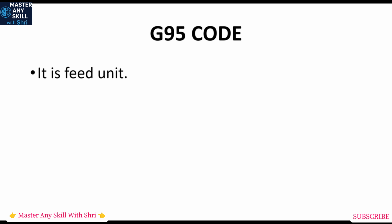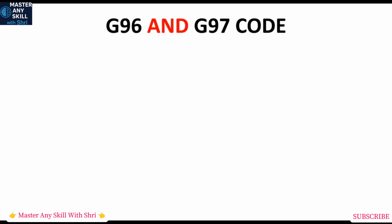So our next code is G95. It is the feed unit. With the help of G95, we tell the CNC machine that our feed is in mm per revolution. That means in one revolution, how much distance the tool has to move is given with the help of feed. This G95 code is mainly used in CNC turning, where feed is in mm per revolution. Our next codes are G96 and G97.